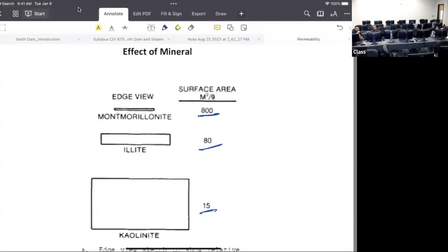It changes the moisture content, right? Now the clay already has the moisture in it, so it's not dry. You try to break it. Will it be broken? Those are like big lumps of clay, and that will mix some part of the lime, but will it be a uniformly distributed mixture? No. There is absolutely no way. So you'll have localized vulnerable spots.